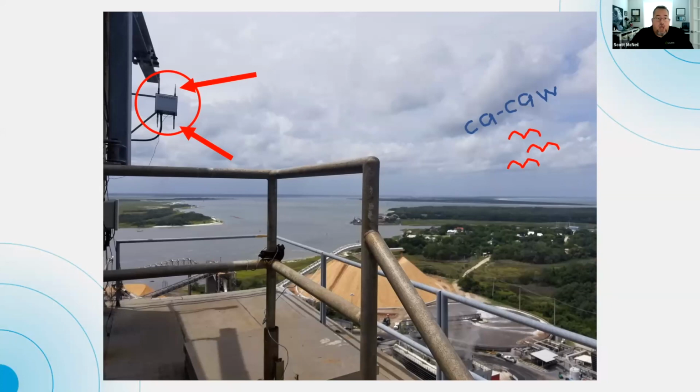So you know what? I don't think it was. It may have been plastic housing, and so they may have thought it was, but it was not like it was IP66 rated. And what's great too is the cable dangling off of it. That was the Ethernet. I'm glad that was really secured to it. No drip loop. You figure you got a loop behind it, but then it's just going down, connecting somewhere back over here, just flopping in the breeze. It's good stuff, man. You can't make this up. They had a bird problem, but other than that, nice.